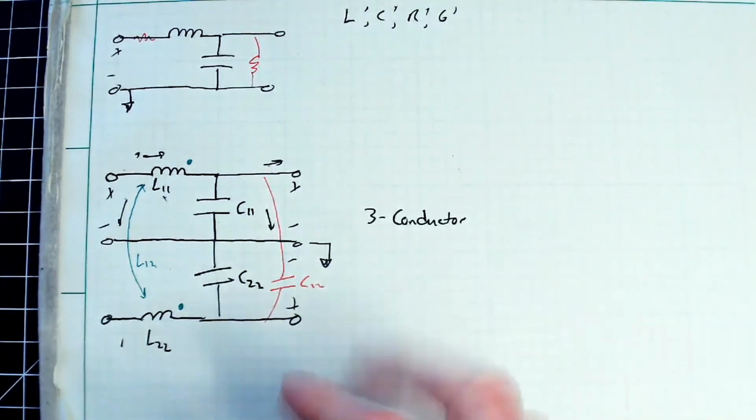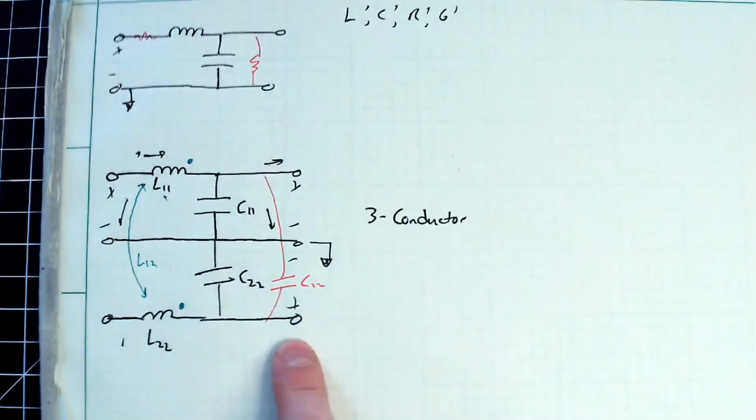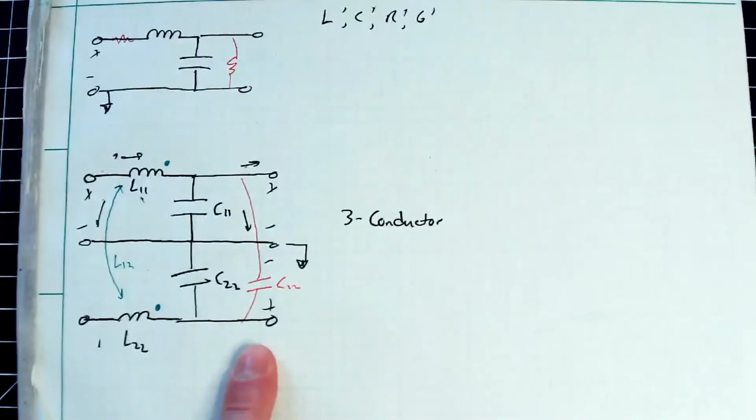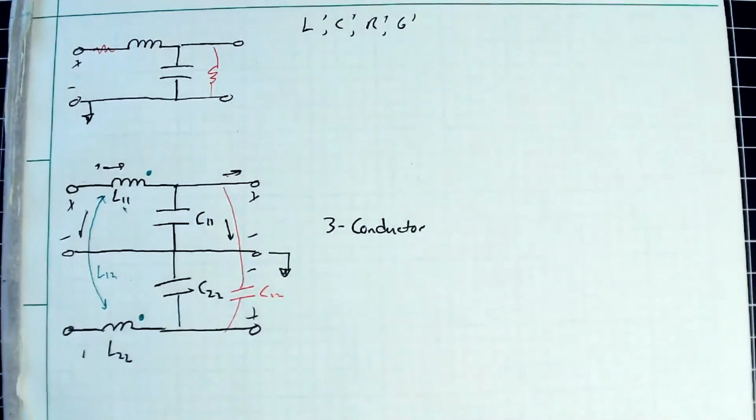So you get a generalized form of the telegrapher equations that has a matrix-vector notation rather than simple coupled PDEs. That is the essence of the multi-conductor transmission line. I think that'll be a nice discussion as a special topic, where we go through the derivation to get the generic telegrapher equations from a model like this.